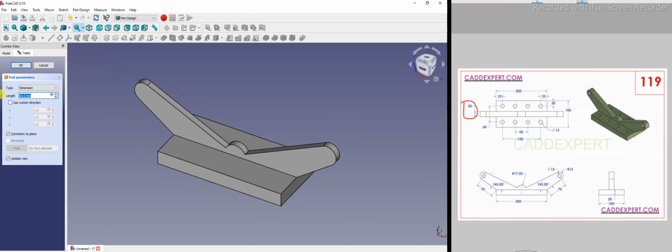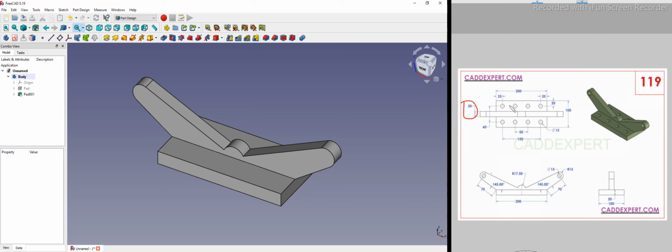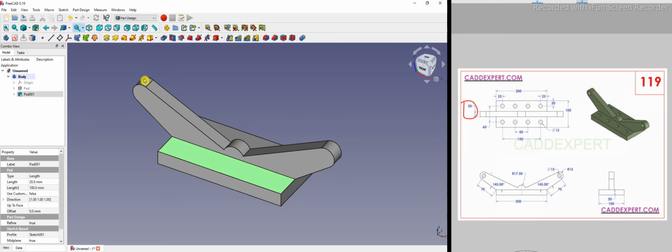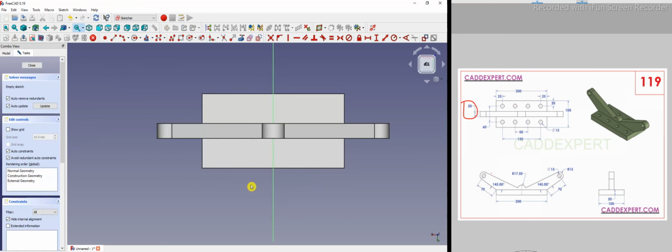Now we will create a hole here, and we will use the linear pattern in the sketch, and then we will make a single cut of these holes. Or we can make a single hole or two holes, and then we can pattern it, rectangular pattern. So we can do it both ways. So hole size is 15, so I will select this face and say sketch.